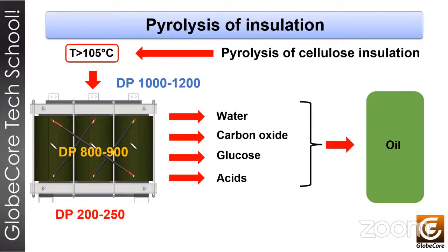The aging does not affect the electrical properties of the insulation significantly, but changes the mechanical characteristics in a really huge way. Aging of insulation during equipment function is caused by the influence of a large number of different factors. One of the most important factors influencing the depolymerization of paper insulation is overheating.